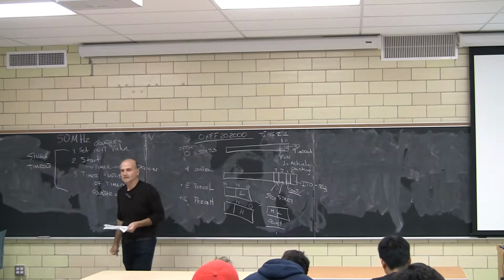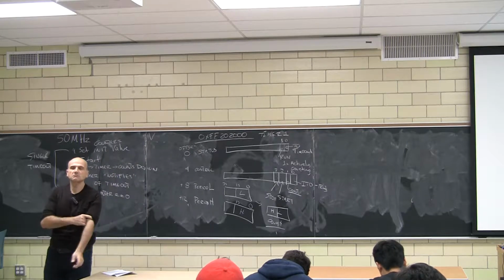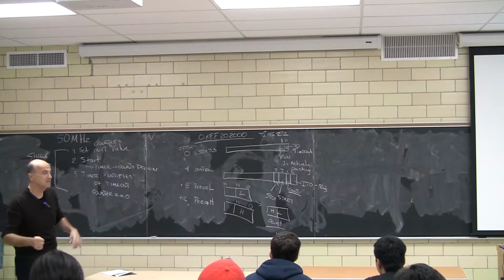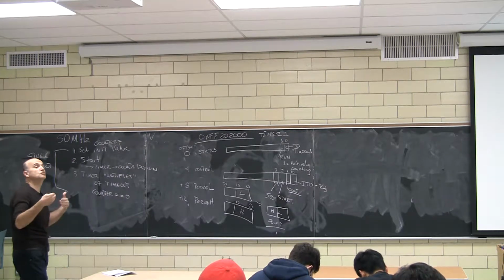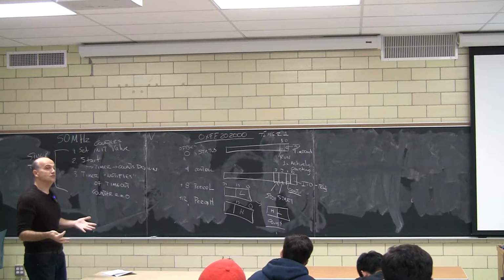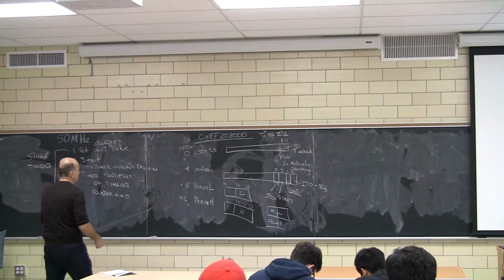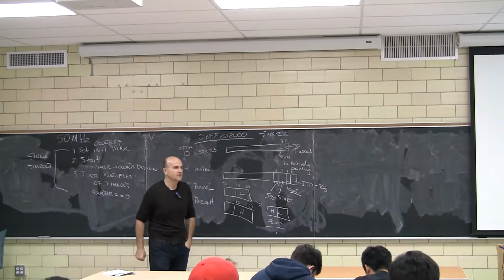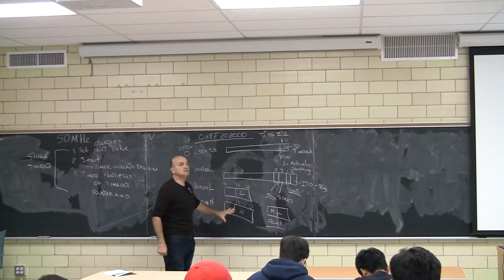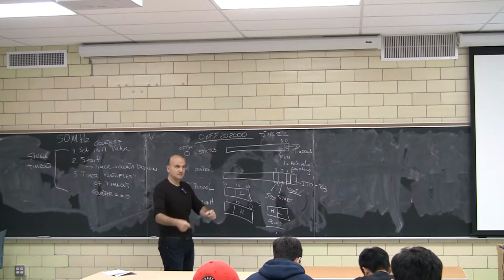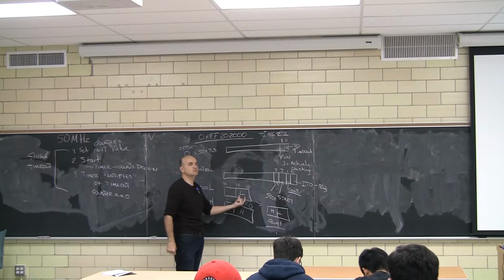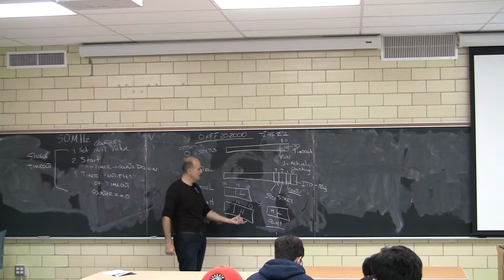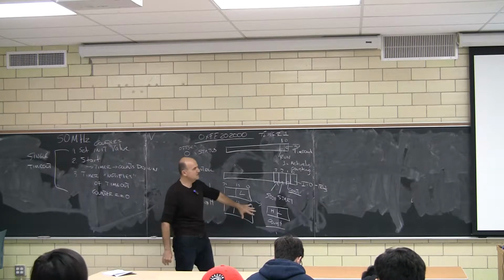All right. Again, for the time being, let's not concern ourselves with why it is like that. This is the way it is. There are 2 registers. The 32 bits, however, only 16 of them are useful. The rest are useless. So for both of them, it's only the lower 16 bits that are useful. They are meant to be interpreted as a 32-bit number together. The lower 16 bits of that 32-bit number come from this register, and the upper 16 bits of that value come from this register. The device does that internally.